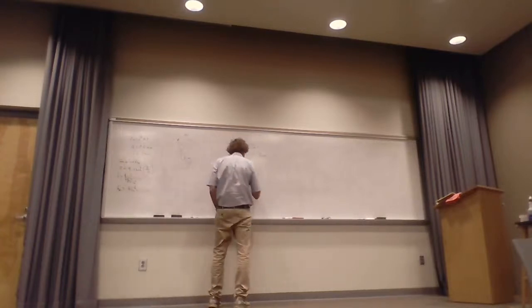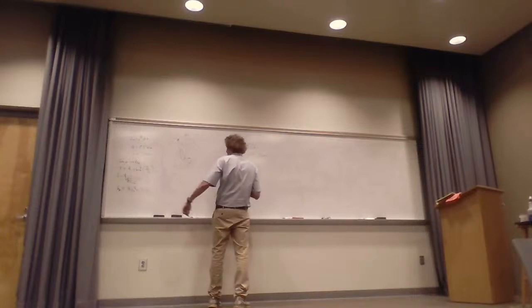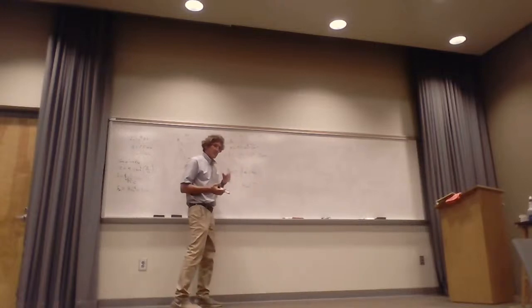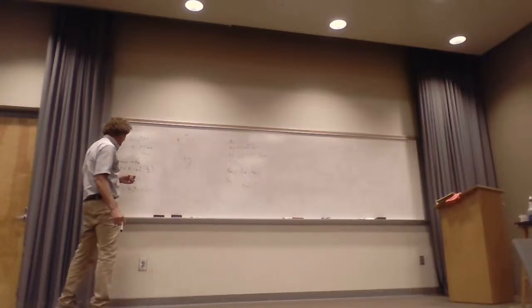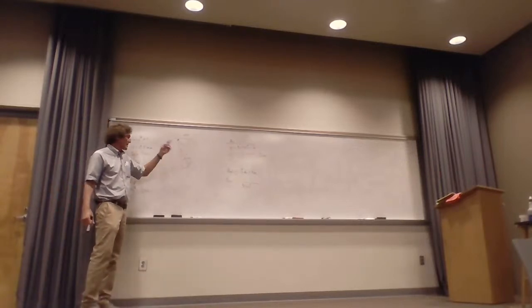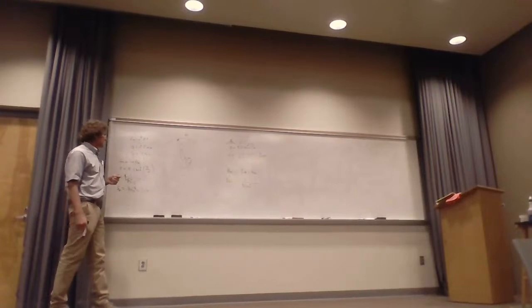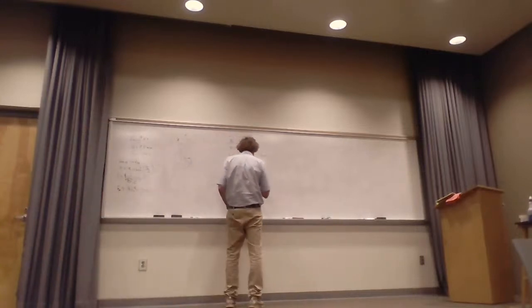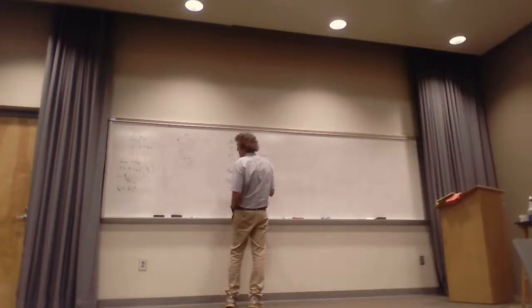It's over sigma, and for gold that's 4.1 times 10 to the 7th, and then times the surface area. The skin depth is microns and the radius is millimeters, so it's much less. We just use an approximation, and say the area is going to be 2 pi a, where a is the radius of the inner one.